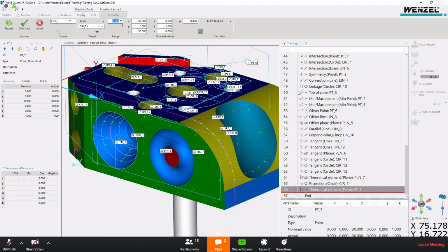Yeah. And then I can set a range, like maybe I want the points within a 0.1 range from the nominal to form the circle. I can also adjust it if I want a bigger range or a smaller range. And then there is the nominal value, and whether it is an inner or outer circle. In this case, this is an outer circle, so it will be this symbol, and this will be the inner circle.